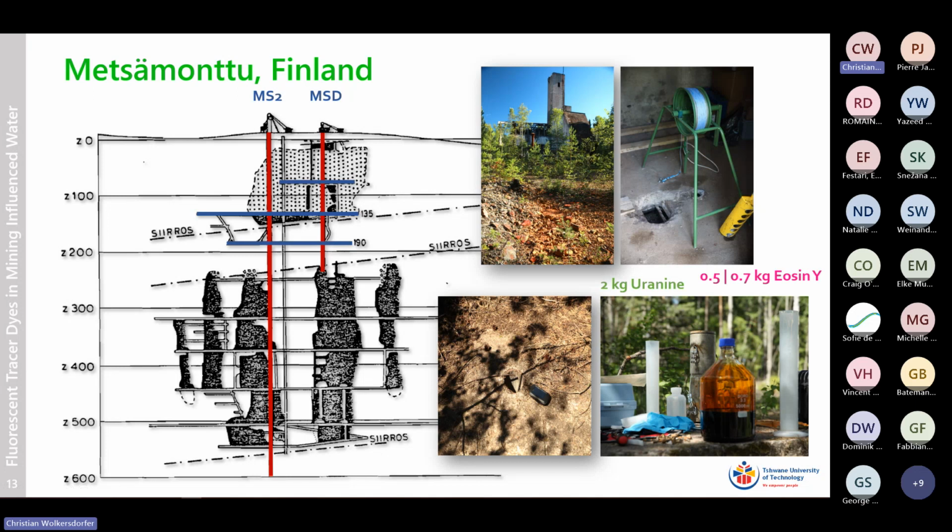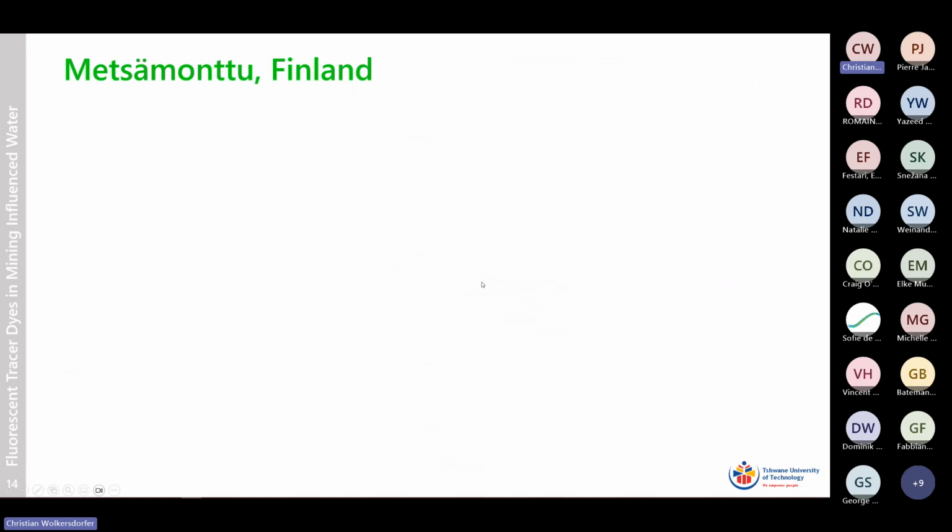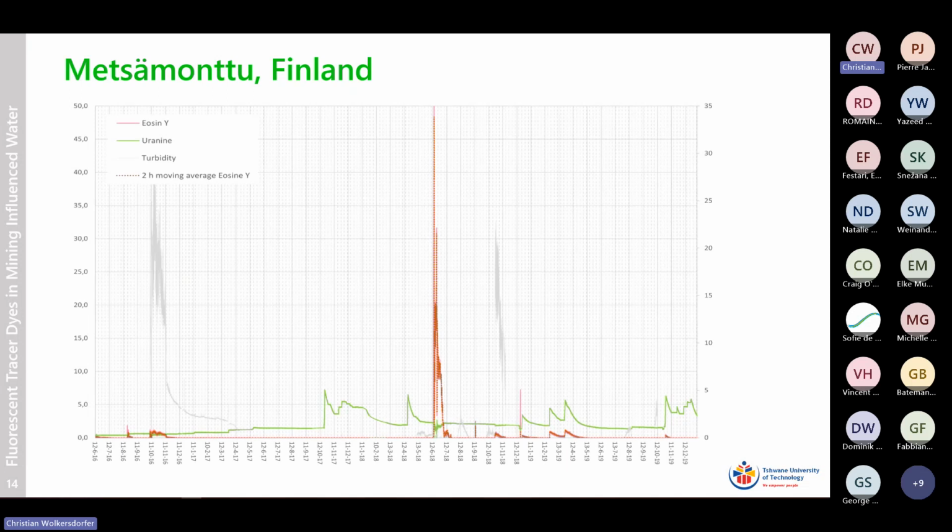Elke already said that we always calculate the amount of tracer we need to use with EHTD. We never use more than necessary to detect it with fluorimeters. We never use too much sodium fluorescein or any other tracer dye. We don't want people to see that we are dyeing streams. So that's the background for it. Therefore, the numbers are relatively low. Let me come to the breakthrough curve, and that looks a little bit different of what you might see.